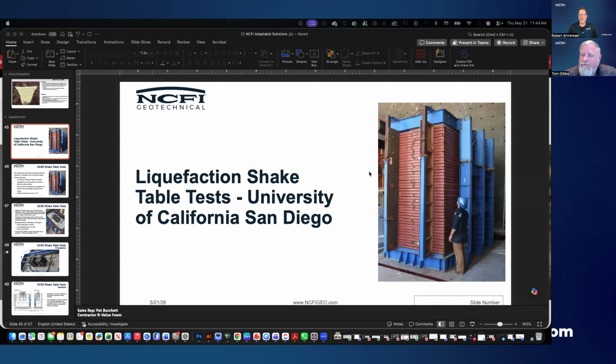I'll add a couple points to that if you don't mind. Typically with expansive clays, the polyurethane is used, especially in deep injection applications in zones like Texas and Arkansas and a variety of other areas that are prone to expandable soils. It's not going to chemically change the soil.